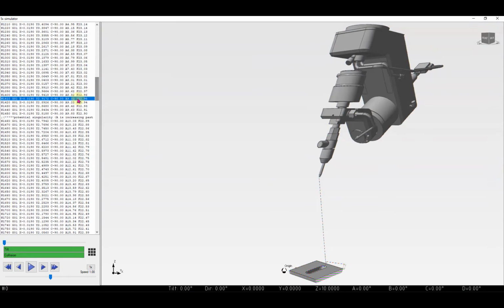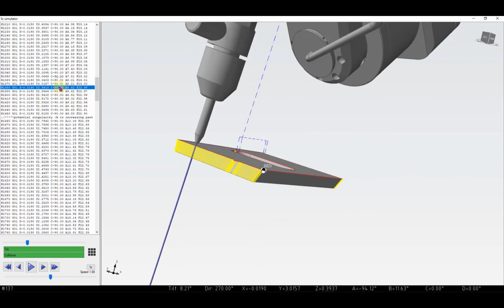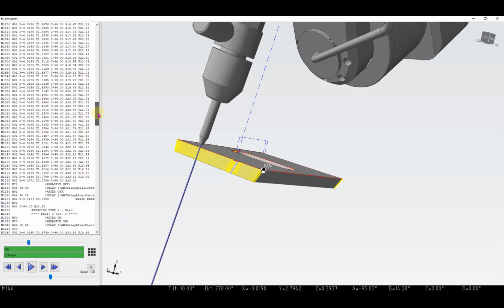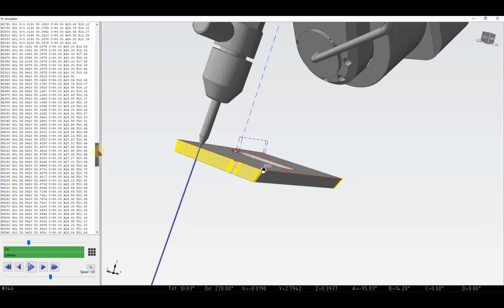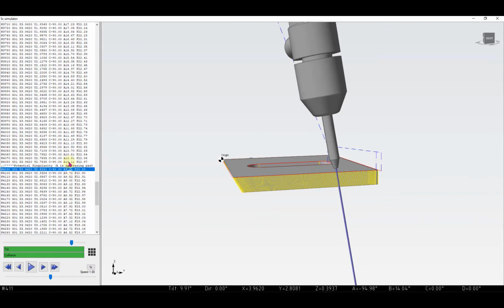As we scroll down here, coming along this edge, our C is at negative 90, and then the A is going smaller and smaller, or sorry, larger and larger, and passes through 10 degrees. We'll have a singularity. The cutting head will spin around there and probably give us a ding on the part. And then after it re-pierces after that tab, going up the other side, again here the A is decreasing and passes through 10 degrees with the C at negative 90.